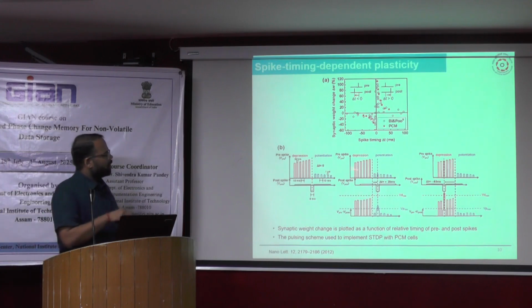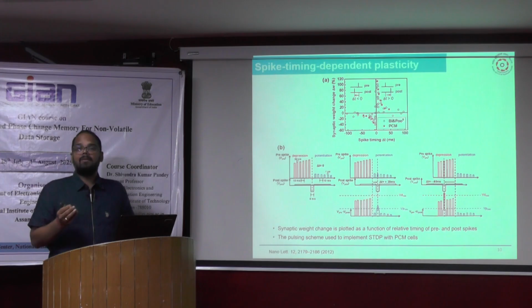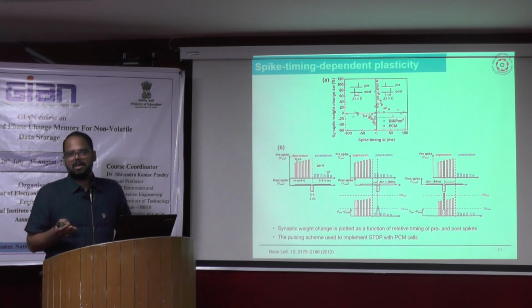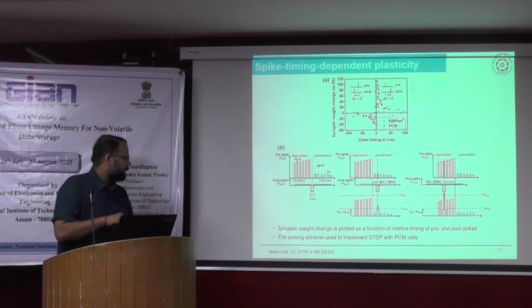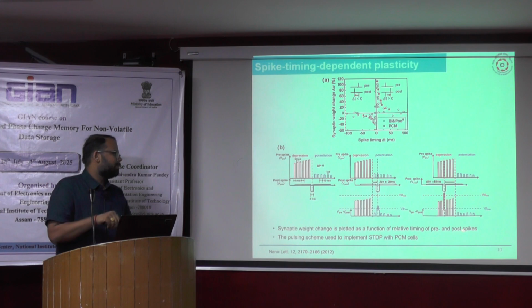The device shows the same phenomena with respect to depression and potentiation. The only difference is that you can have better control and easily tune to a particular state. The synaptic weight change is plotted as a function of the relative time of pre and post spike, along with the pulse scheme used to implement STDP with the PCM cell.